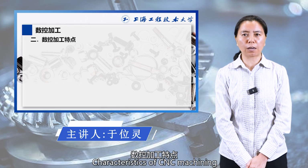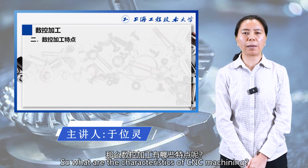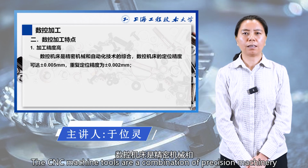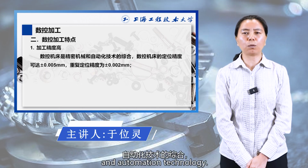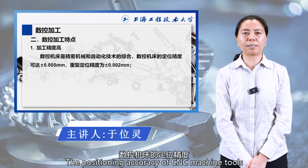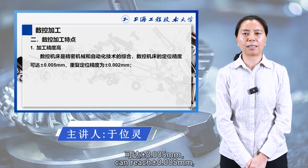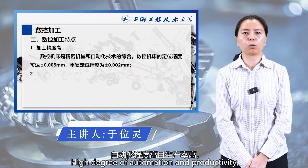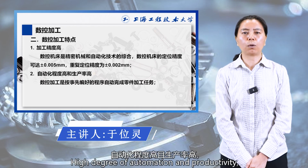Characteristics of CNC machining. So, what are the characteristics of CNC machining? High processing accuracy. CNC machine tools are a combination of precision machinery and automation technology. The positioning accuracy of CNC machine tools can reach plus or minus 0.005 millimeters, and the repeated positioning accuracy is plus or minus 0.002 millimeters.